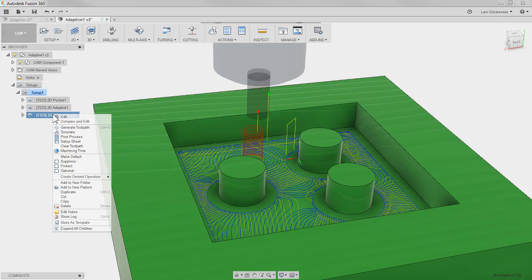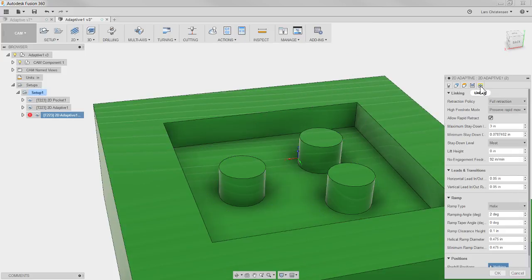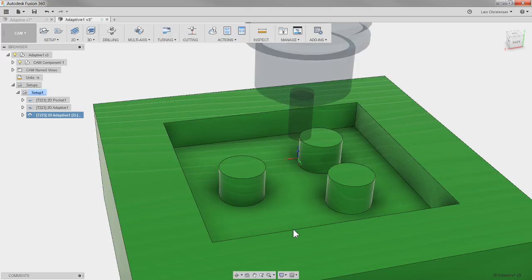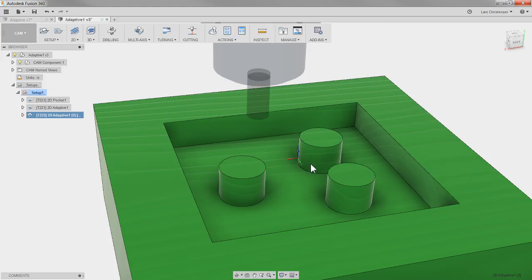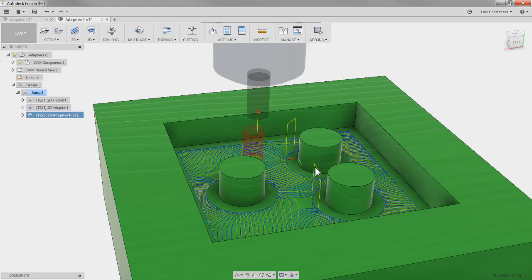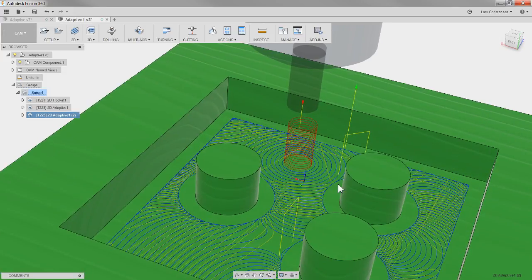So what I normally do when I am doing these is set this one to a high number, and then if it's a big toolpath and I don't want to wait for it to calculate too much, you might just set the stay down level at like 50%. So set this at 10, 50%, and hit OK. This is kind of like my normal setting. And you will probably see that now I'm ending up with 2 rapid moves, right? So it's somewhat faster calculating, and we're only getting a few quick rapid moves.